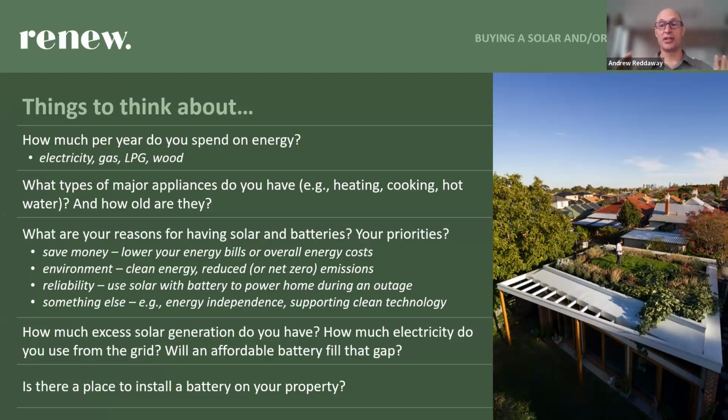You also have a really big opportunity to get big savings through solar and batteries. Think about your appliances. How much of them are electric? How much of them are gas? Are they reaching the end of their life? Might you switch over some of your gas ones to electric in the future? If that's the case, then your electricity consumption might actually go up, and in a good way, because you're avoiding that gas consumption. In which case, that may justify a bigger solar system.